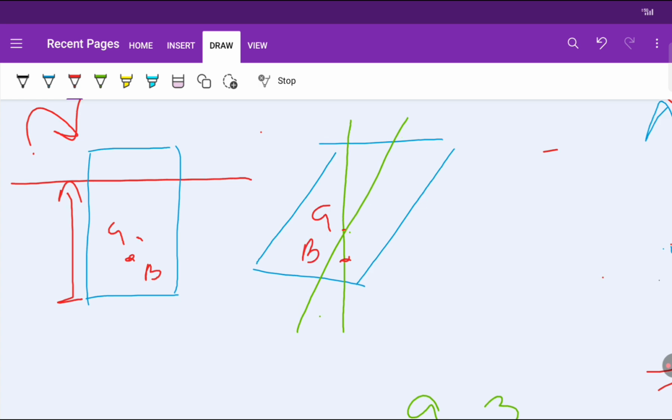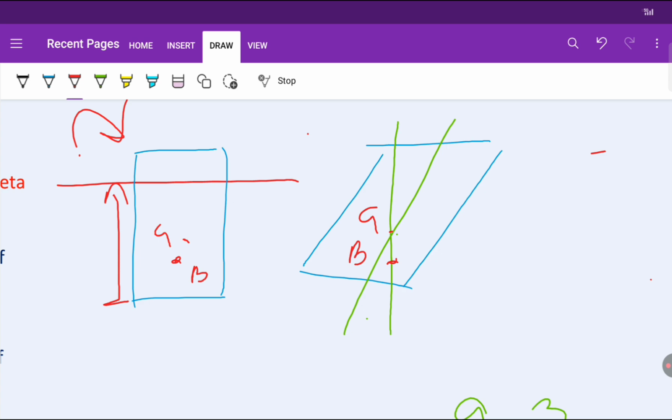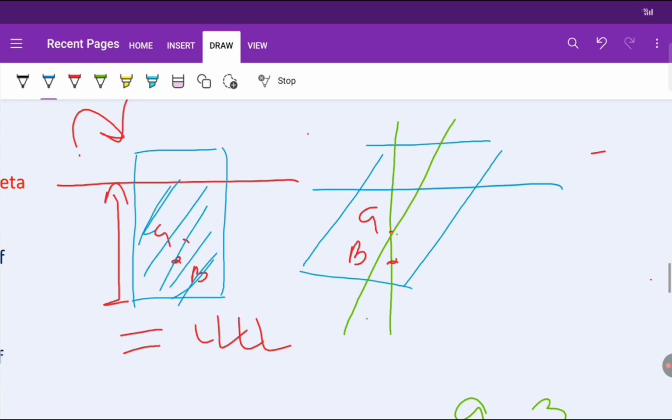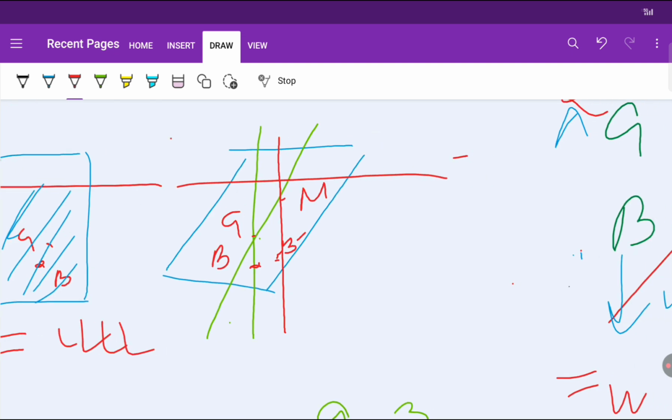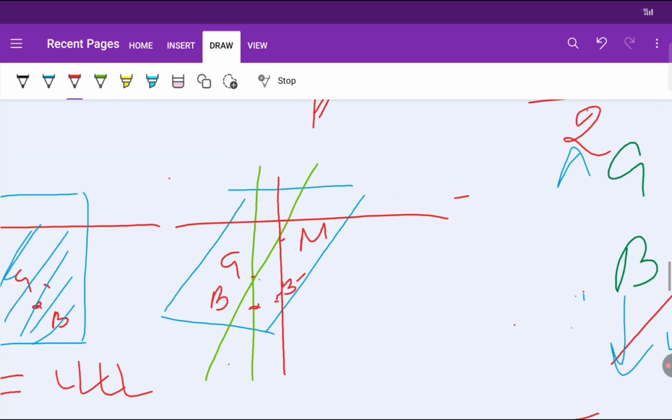Okay. Now in this case, the volume displaced has changed, because when you give an angular displacement to this floating body, the volume of water displaced also changes, right? So the buoyancy will also change. Our new center of buoyancy, suppose here, is this, okay? If I extend this line, it will intersect somewhere here. This will be our metacenter, right? So this is our new center of buoyancy, and this is our buoyant force FB,